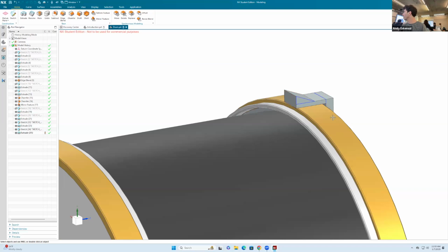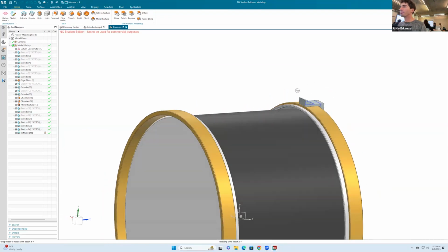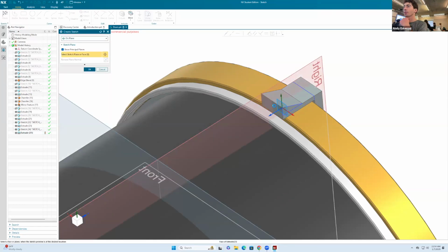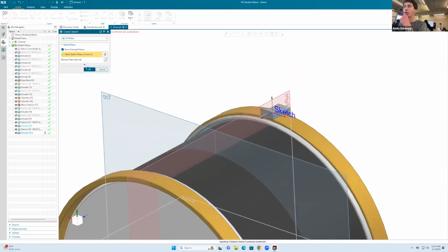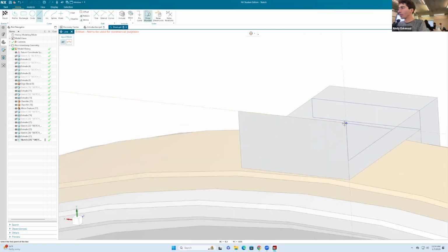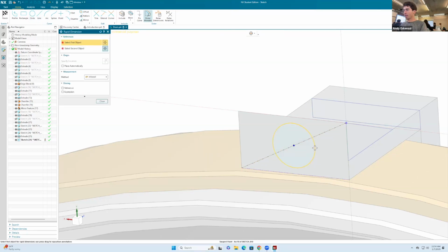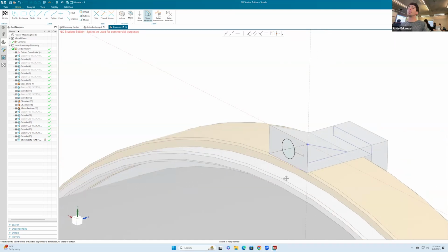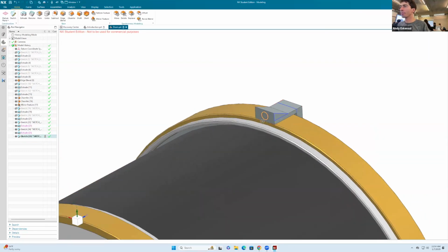You see, you can start adding a lot of fun details with all of the tools that we learned today, just different shapes. And now, the next thing I will do is a little sketch over here. I'll say okay, and I'll define a line to go from here, and then I'll make it go there. Right click and make it construction. That way, I can now draw a circle that's going to be on the middle of that line, and I can make this circle be 2. Just like that. So we're gonna make a simplified design for this thing.